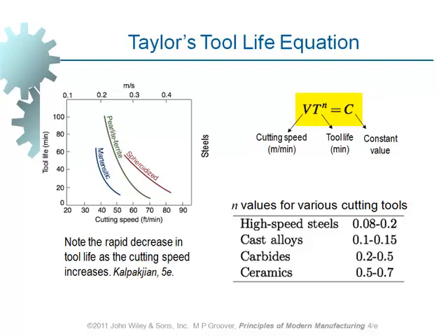Do you remember the previous slide that I had? For a cutting speed of 160 meters per minute, the life of the cutting tool was only 5 minutes. We lowered the cutting speed from 160 to 100, which resulted in an increase of the tool life to 41 minutes. So the difference that cutting speed makes in the life of the cutting tool is really, really big.